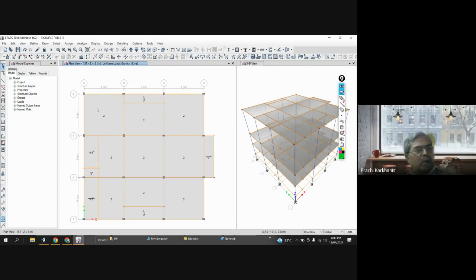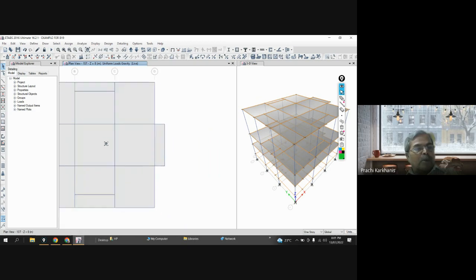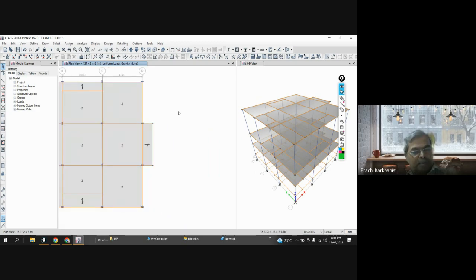See, slabs are not designed for resisting point load. There the arrangement is a bit different. Then you will have to create some additional support below that point. Let me understand where that point load will come from on the slab. Okay, we'll go through that, because there is no point in going ahead without understanding. One minute, brother.